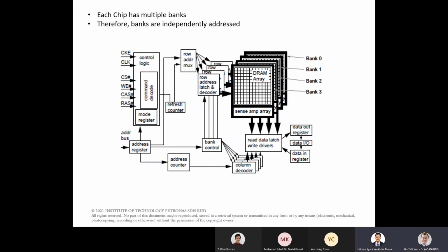Okay. Do you see how this is used? Yes. Okay, so we have banks in order to parallelize the accesses, and this is where the command comes in. You can start overlapping. Just because your first read or write command is not yet finished, you can already send the next one, and that's why you have some kind of decode logic to be able to receive that. Do you understand that?